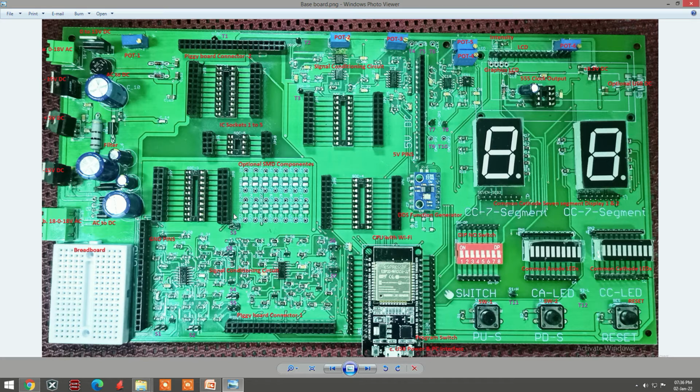It is a serious problem because you are also going to use SMD components, and the tracks are drawn below the ICs. So once you mount the components, it is very difficult to trace where the short circuit is. So you are not supposed to mount any components yet. Though we are giving a fabricated PCB, make sure first to give power to the board, or if you have a multimeter, check the continuity between the power supply and ground. There should not be any short circuit.